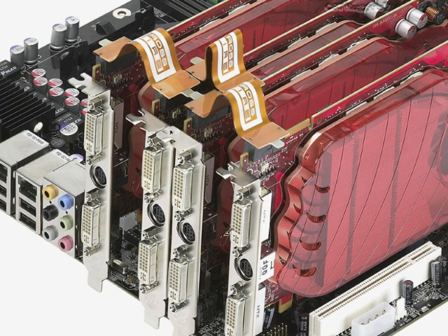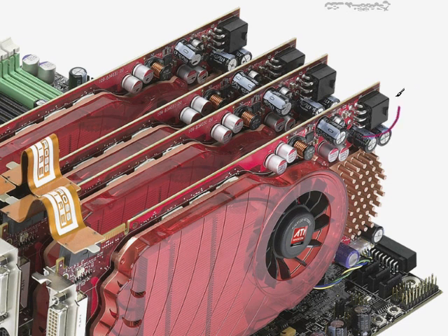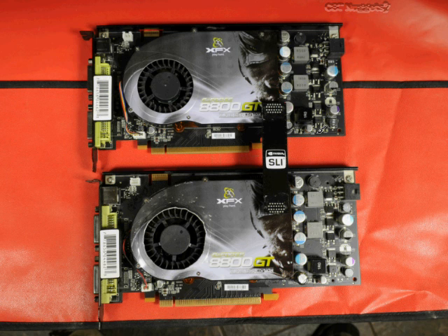But again, we would gang these together so that we would have all the video coming out of a single card, for example, and it would get the aggregate performance of all of these cards put together. Again, all through these connectors, you daisy chain each one of these one after the other. Also here on the end of these, I was telling you they need their own power supply. This is where the connector would go for the power, and you'd have to make sure, of course, that your power supply was able to supply power to each one of these as well with appropriate connectors. And those ATI cards use their branding called Crossfire to gang those all together. And as I mentioned earlier, NVIDIA uses SLI.